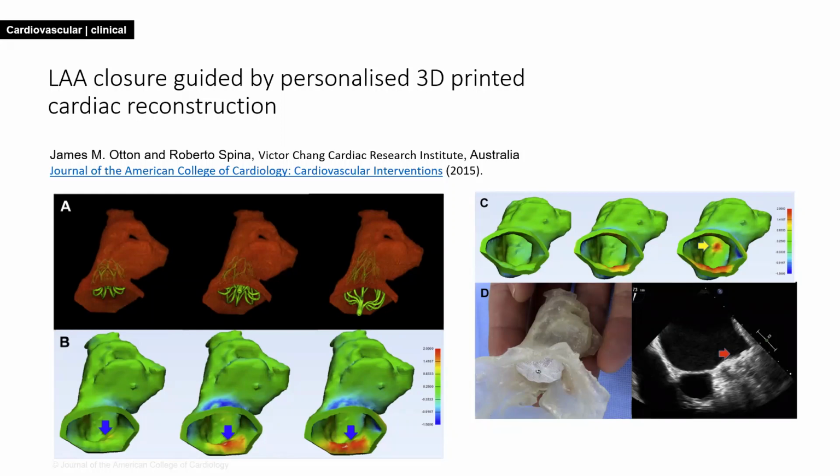They did a CT scan of the left atrium, and the left atrial appendage was obtained and imported into Mimics, where a 3D reconstruction, semi-automated segmentation was performed in the software. This was then converted into an STL file and printed to simulate the mechanical properties of the atria.